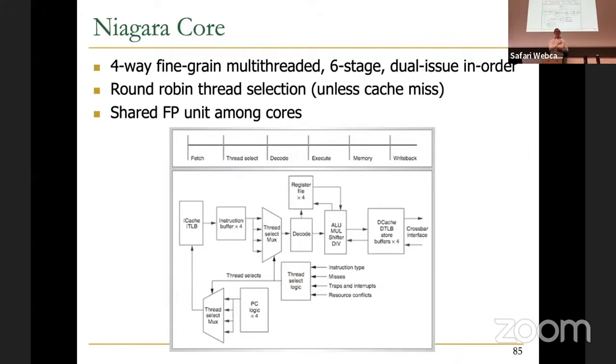So let's make cores more and more powerful. And that's why they were going with run-ahead, for example. They added run-ahead to make each core more powerful. And then they were actually adding this simultaneous speculative threading that I mentioned when we talked about run-ahead to make each core even more powerful. So they figured out these small cores were not really that good in the end because of the bottlenecks.